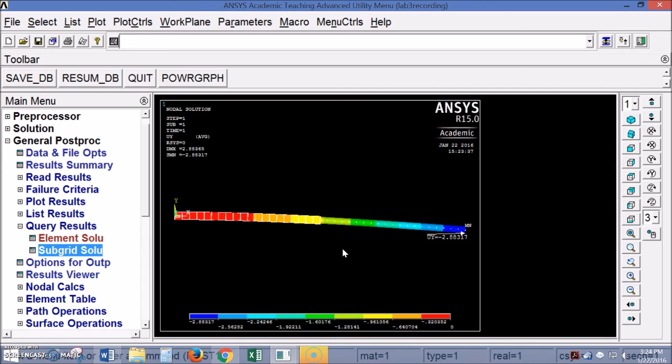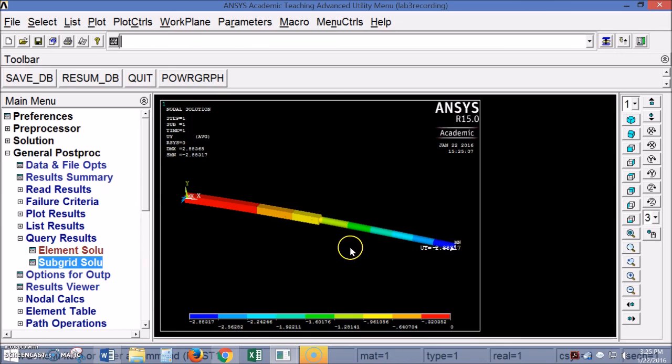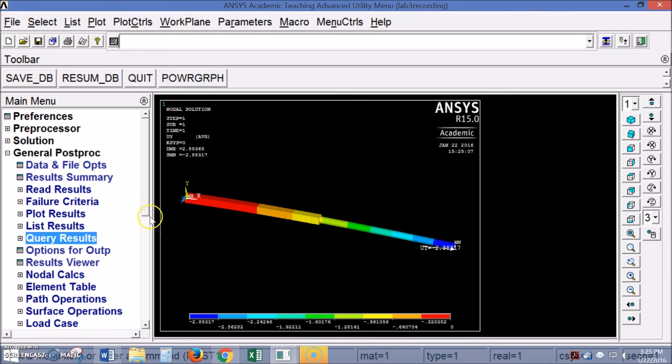And if you can think back to your other classes, one of those is going to have a greater deflection than the other, and one of those will have a maximum stress in a different place. So for the point load, the maximum stress should be back at the wall, but for the distributed load, it might be in the middle. Actually, I might have reversed that, but one will be at the back of the wall, and one will be in the middle of the beam, right at the top of this. And if you think about your VQ over IT and equations like that, you can kind of put together why the max stress is on the top of the circular section in the middle, even though the moment arm is so much shorter there.